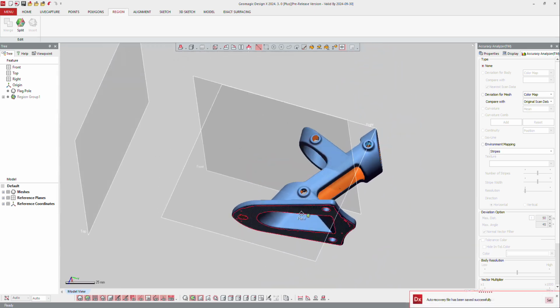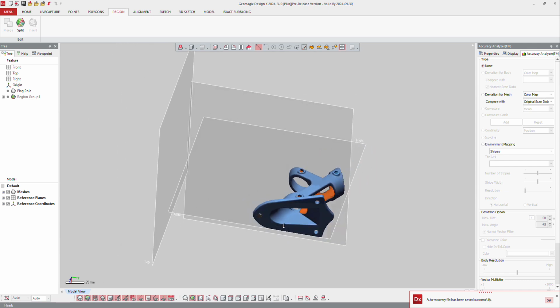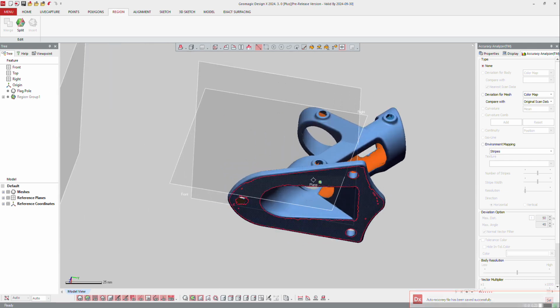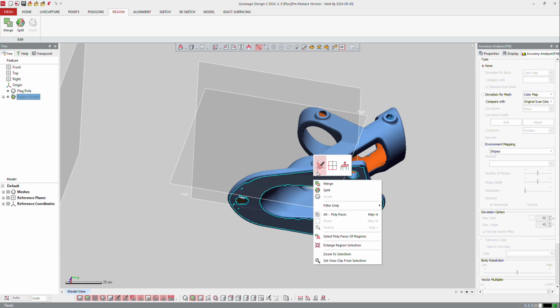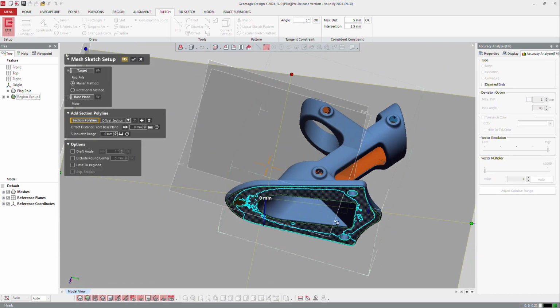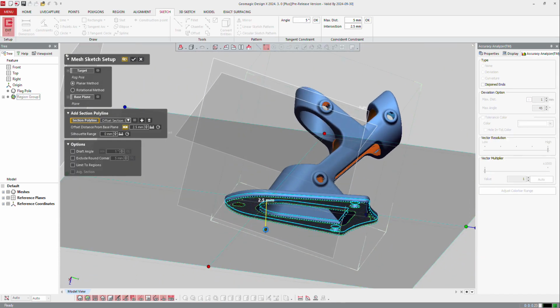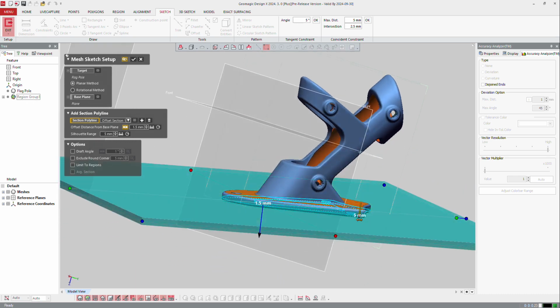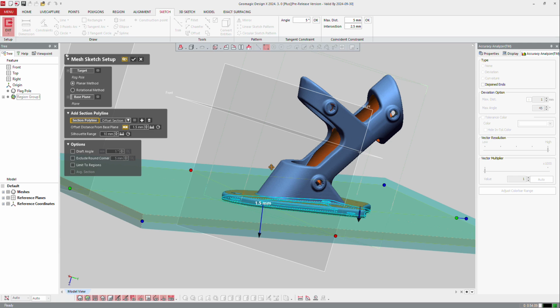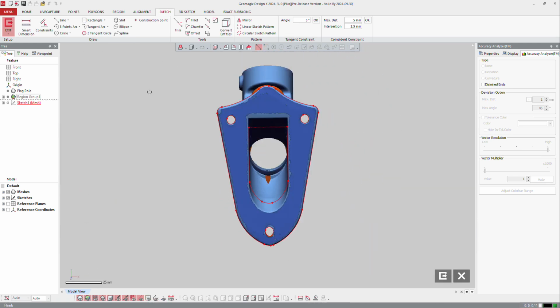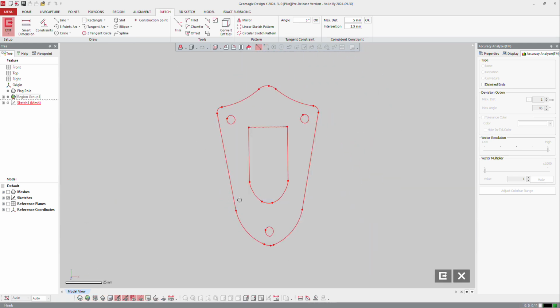So I got different methods, maybe symmetrical planes, but here on the part I can see some holes. So I will make a mesh sketch here, and maybe move this sketch a little bit higher just to get the two holes. If I don't get the holes, I can increase the silhouette here, and I press OK. I switch my screen with Alt space, and now I got three circles right here. I will get my circle here, my circle there, and my circle there by double clicking.